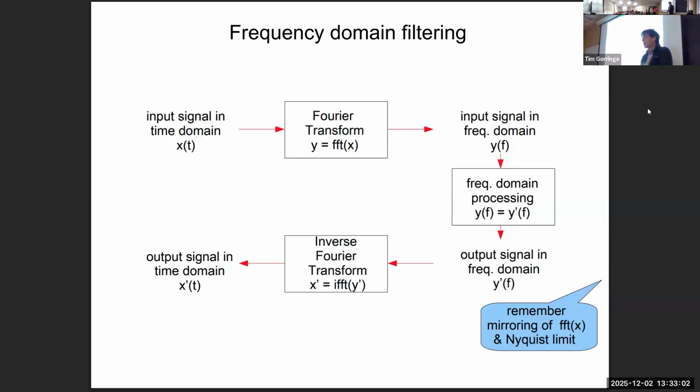But you might think, well, we met earlier on Fourier transforms between time domain and frequency domain. If I want to reject, say, high frequencies, extinguish those and keep low frequencies, why don't I turn everything from the time domain into a frequency domain and apply a frequency cut in the frequency domain, where I can make that cut extremely sharp? Why wouldn't I do that? Well, you can do that, and that is done. The challenge with it is that you can only do it in some applications.